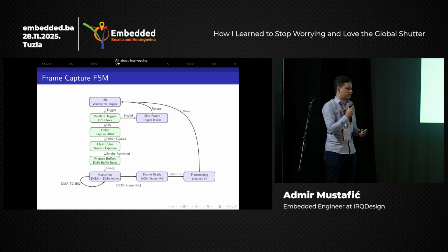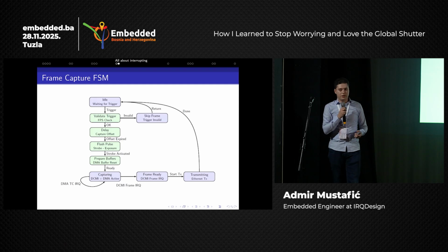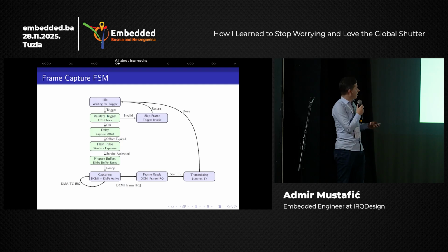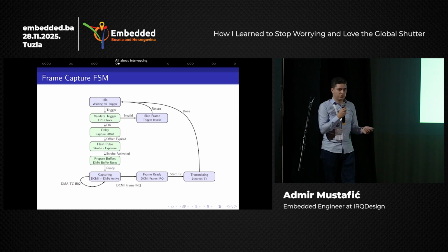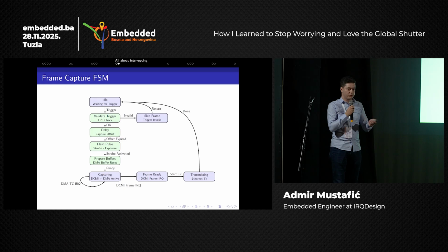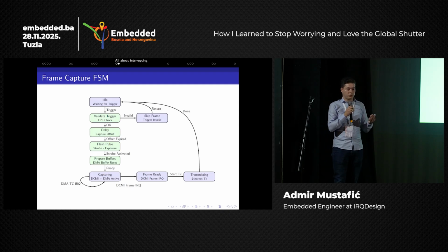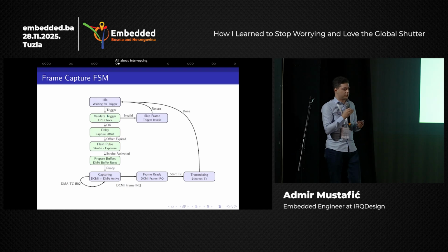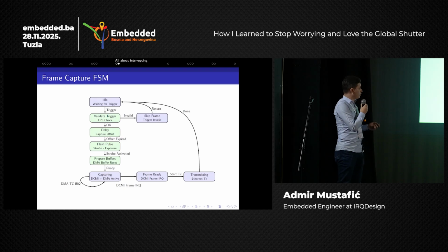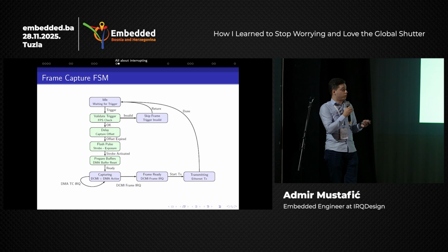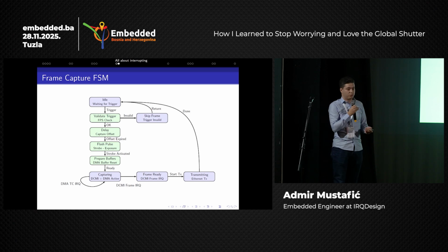So we have, for a certain resolution and data width, the maximum frame rate we can capture. If the frame rate of the external synchronization signal, for example, a rotating wheel, is much faster than the maximum frame rate we can handle, we cannot capture such an image, since during the capture procedure itself, the image will become corrupted and we will not be able to send it at a proper time.